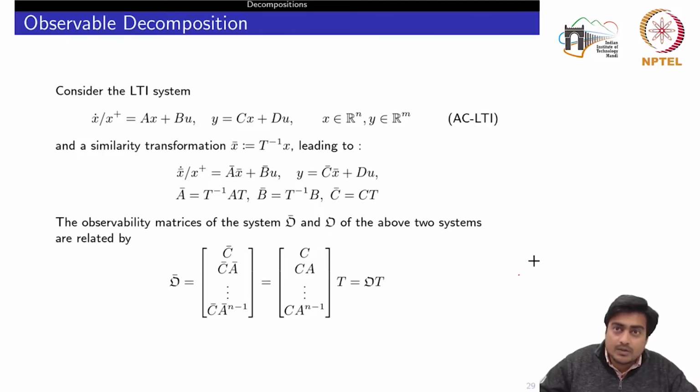So far we had discussed the results on how to determine observability, and basically it requires satisfying some rank conditions on the matrices. Now if the rank conditions are not satisfied, say for example for the continuous time LTI system, if the rank of the observability matrix is n, then the system is completely observable. Now if the rank of that observability matrix is less than n, then it means that I cannot observe all the states. But is it so?